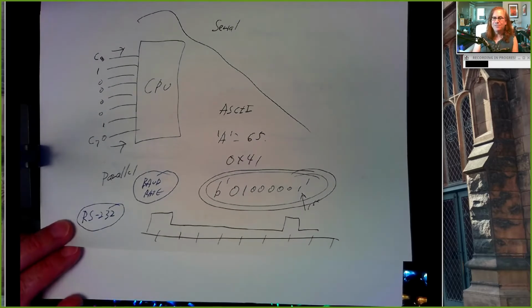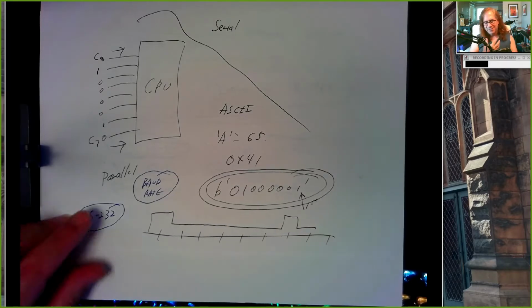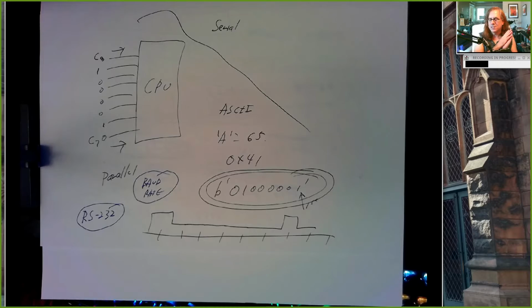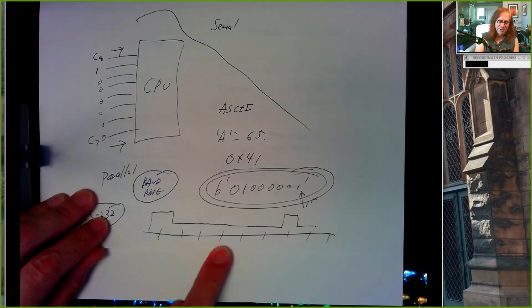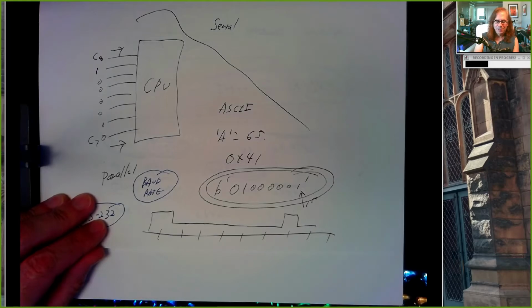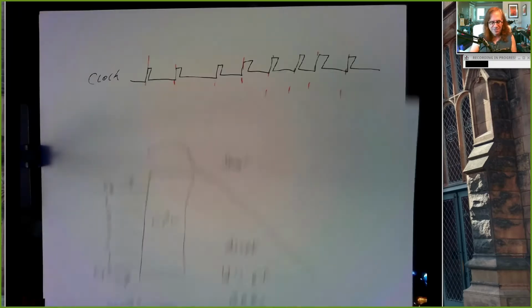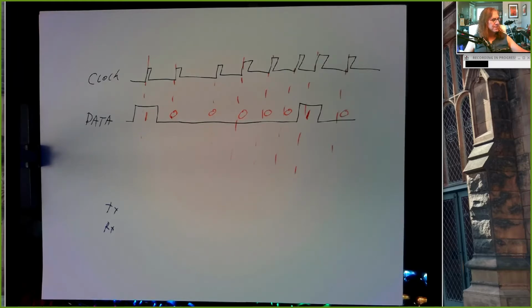But if you do that in software, that's all that your program is doing. So we have these subsystems built into the hardware that'll do this for us. But sometimes, all you want to do right now is just send a character out or receive a character. You can just write some code, and as long as you know how to manipulate the timing correctly, you can do all of this just in software. And that can be fun. It's really cool because you think of languages that can be built on top of C, because C is this common ground, and whatever the application of your programming language needs to accommodate, you can just build it on top of C. But you can basically do the same here with serial communication. Exactly, yeah.